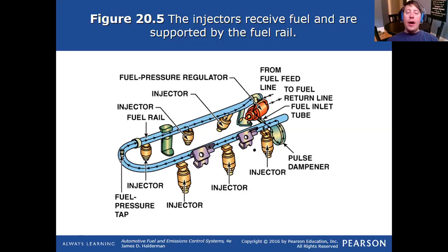And so you have this constant increase and decrease of fuel pressure and flow and volume happening inside the injector. And what can happen is you can end up with an inconsistent fuel flow in the rail. So I just talked about how the manufacturers need to have everything they design for pulse width on an injector based off of a guarantee that there will be X amount of fuel available at that injector at all times.